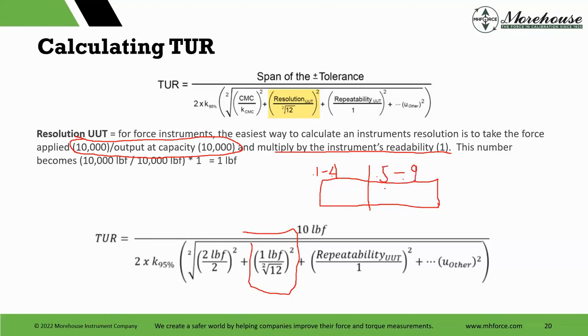Between this imaginary digit, we do not know where it's going to fall, and therefore I have two-sided probability. I drew this intentionally, but it's not a perfect rectangle. Each one of these is the square root of 3, and since I do not know where it is going to fall, if I take 2 times the square root of 3, I actually get the square root of 12. This is why you see resolution as the square root of 12, or 3.464.